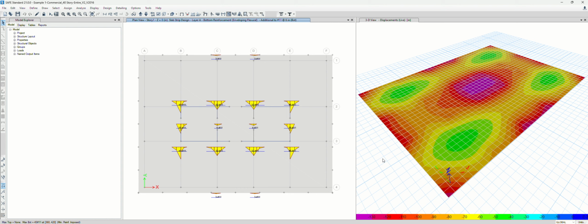This stress, soil bearing, is pushing uniformly, so the footing will experience cantilever bending moment, right? So that you could just check the shear stress and shear capacity, and also bending, using the bending moment for your rebar design. So I just want you to see this more globally. Even though this is a huge scale, it's nothing different. So you need to exercise this.